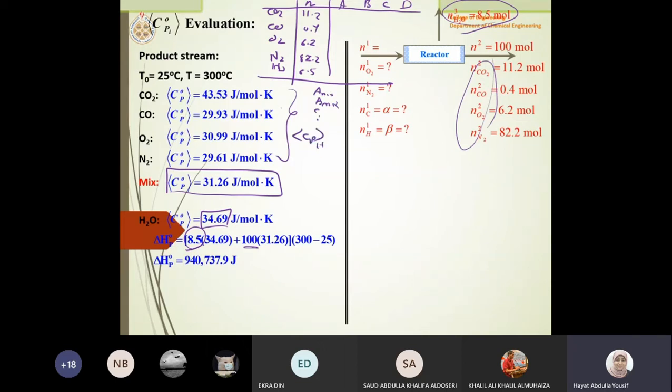What do I mean by once? It means I don't have to repeat that calculation several times. CP mean once means I will find the CP mean in joule per Kelvin. Once I get it in joule per Kelvin, it's just a representation for all that. It replaces all this. Okay? So that CP mean, I will just need to take it and multiply it by the temperature difference. And the temperature difference, you know what?